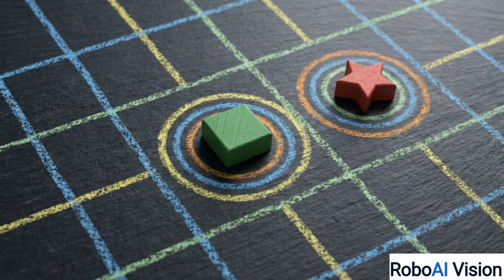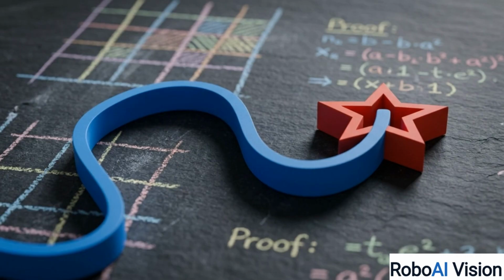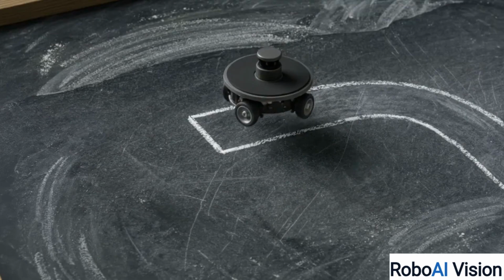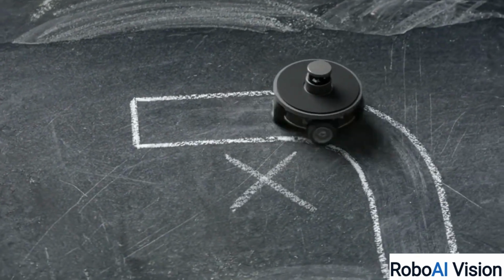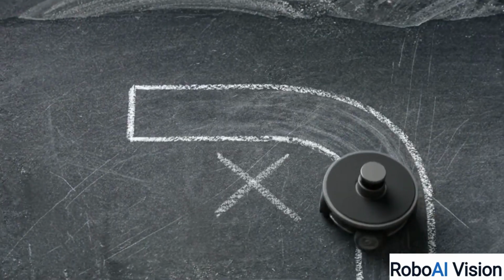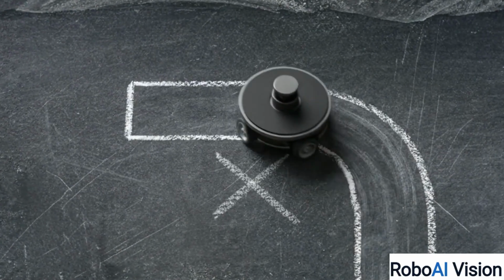To ensure the robot actually begins and ends exactly where it needs to, the algorithm employs a uniform clamped knot vector. Clamping mathematically forces the generated curve to intersect the very first and very last waypoints with zero deviation. This parameterization laterally rounds off the sharp interior vertices for dynamic stability, while locking in the exact start and goal states required by the mission.